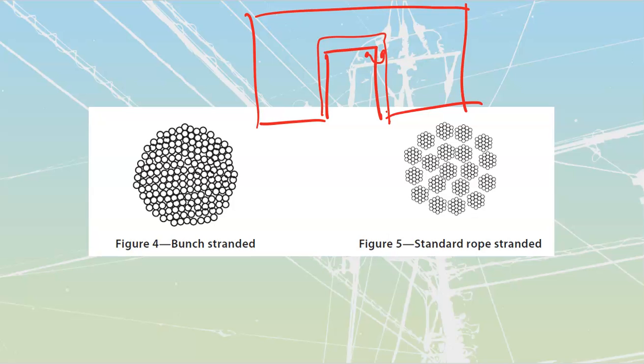We'll also see it used for, if you've ever seen a pole top switch, that's going to be one of those ones where you get the pole coming out of the ground, and then mounted on the side of that, there's going to be this bracket with a long arm that goes all the way up to the top, and then there's going to be this bar that's going to come out of there, and you can use that bar to switch back and forth. There's also going to be a ground mat that's going to be underground for them. And all of that needs to be bonded together so that my operator is going to be safe. We will do that usually with flat braids.